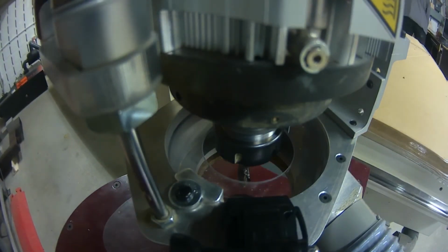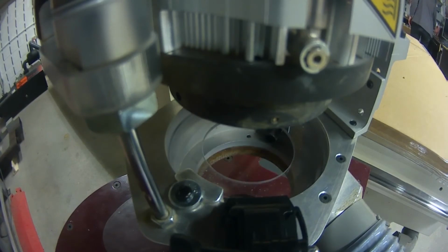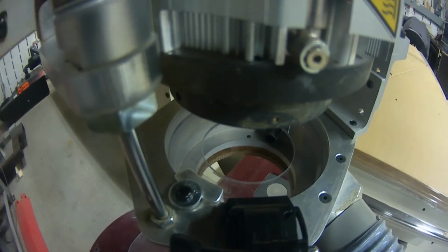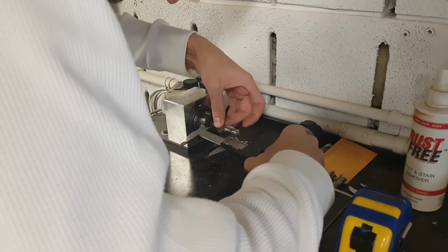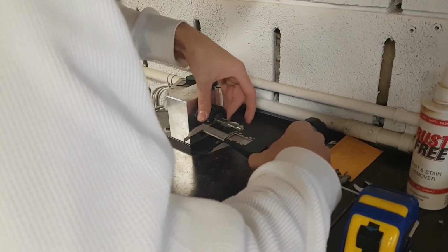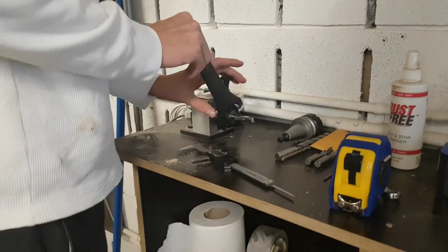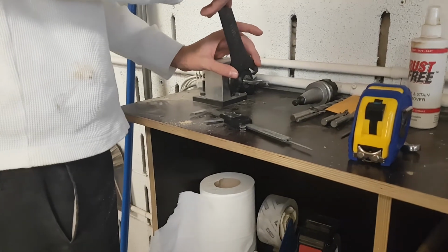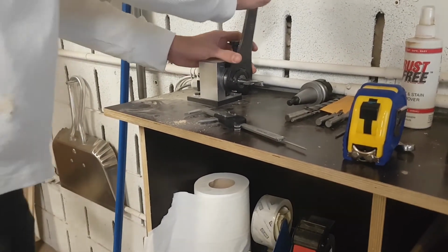Do not take the initiative to modify the tool dimensions yourself, as changes that are not coordinated with the rest of the machine may lead to it being damaged during the operation. There is a plethora of available tool bits that can be utilized with the CNC machine. Once the ideal bit is selected after proper consultation with the workshop staff, it then has to be secured into a tool holder, have its dimensions inputted into the RhinoCam UI, and then calibrated with the CNC machine.